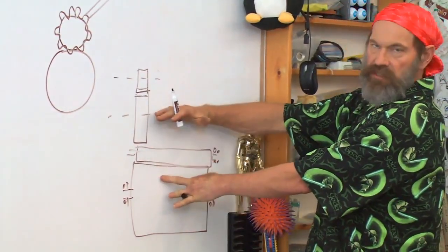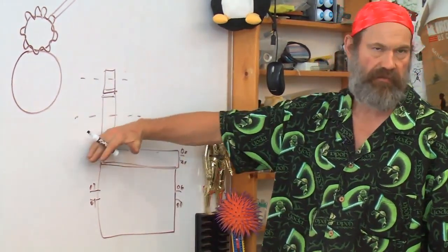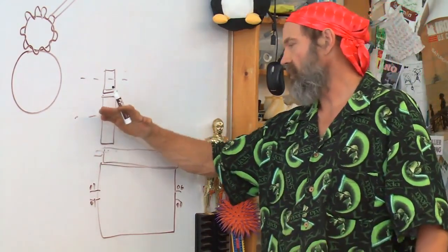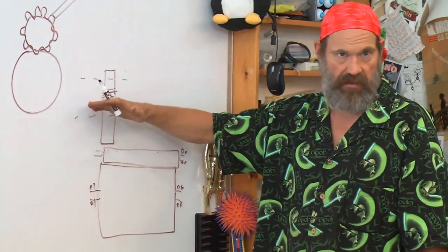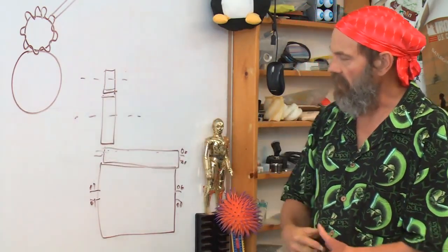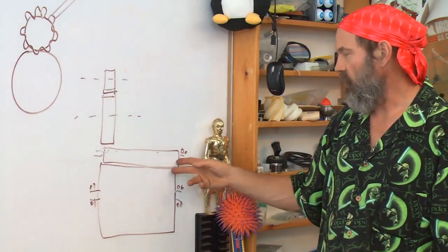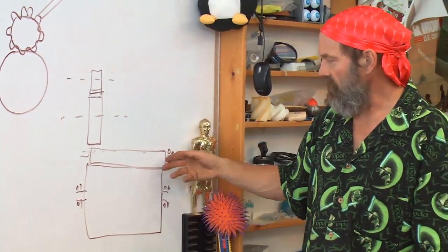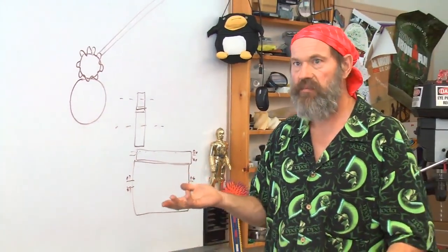Well, there's gear tooth separation forces, which would cause loads across the gear, which would cause the shaft to bend, which would mean the teeth are engaging not uniformly. If the shafts are misaligned by a small angle, that small angle is amplified by distance. This is the Abbe offset we were talking about. And you will, again, have different engagement areas of the teeth, such that there will be a point on the tooth that takes more load and it starts to wear first. It'll wear first, and that's when the whole thing cascades and starts to fall apart. How wide can the gear teeth be?